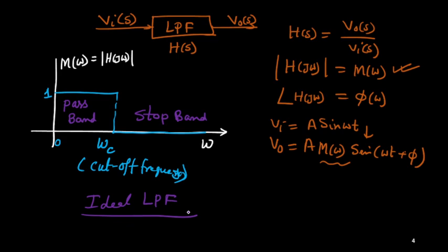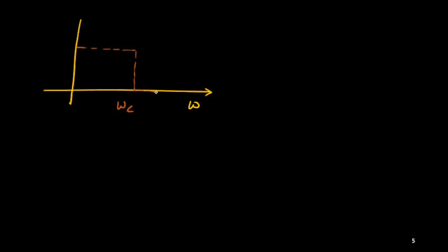Now in practice, how to design a low pass filter using capacitor and inductor, that is the most important part. If we want to design a low pass filter like that, what will we do? Before that, what will the practical magnitude plot look like? Suppose this is the omega axis and this one is the ideal plot, up to omega c and beyond that it is 0.